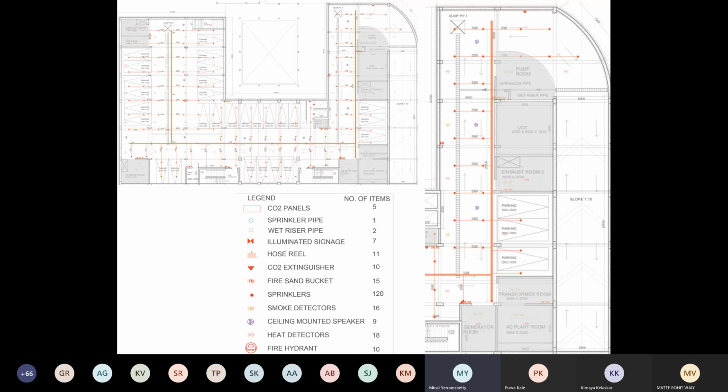Okay, in academics we do that. But in real life people use smoke and heat detectors in all M&E rooms, because sometimes a machine might be heated up and it requires cooling off. The heat detector can really tell me all this. It will not give off fire, it will not give off smoke, but it will heat up, and that heat can build up, which can lead to serious accidents, and heat detectors detect this. So before the fire takes place, I am aware and can take care of it.